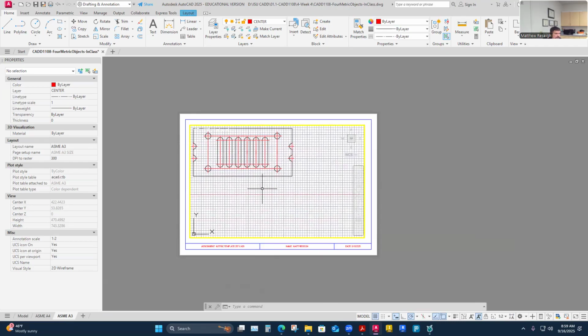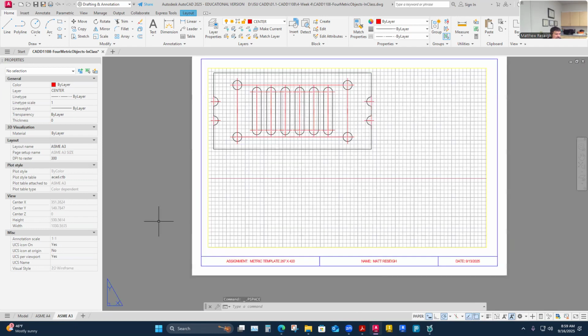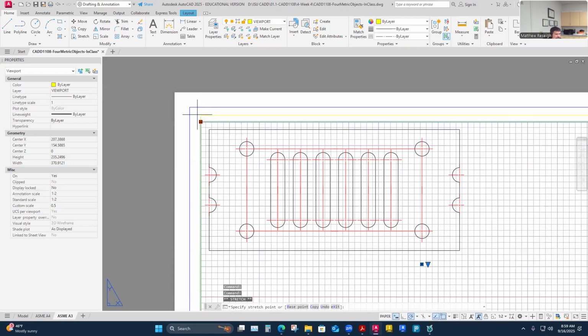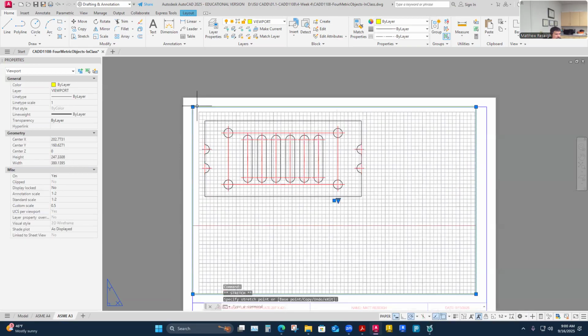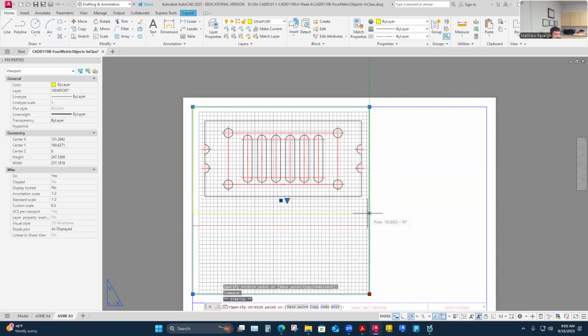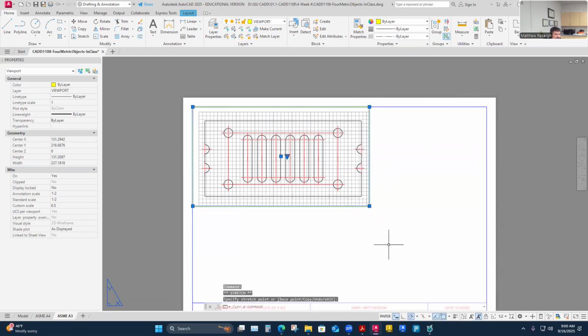So here's how you deal with multiple viewports: I just adjust them so they only fit around this object. So I'll jump back out here for a minute and adjust my viewport size. For this one, I'm going to drag it almost to this border because I'm going to use this whole upper corner. But I don't need it to be that wide. I only need to show this much of my object. Just don't cut off your object, because it will, right? That'll cut off my object, however I put my viewport. So make sure I see my object and then just adjust this viewport so that I'm only showing my object like this.